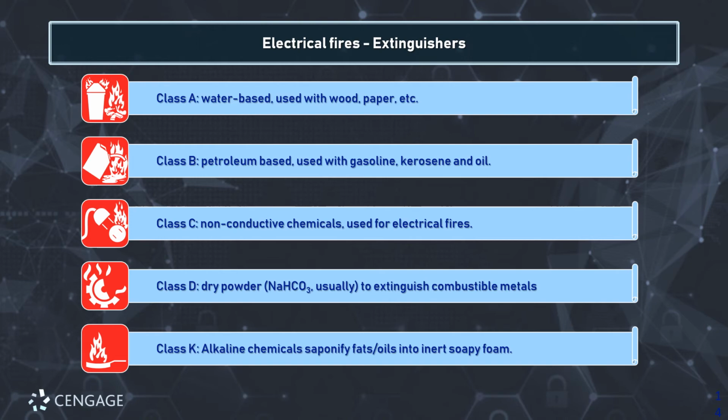If you do that with oil, because oil likes to form very similar in biology to what we call a lipid bilayer, it takes these little bitty pockets of water and spreads them out, and it gives them just enough insulation to where they don't flash vaporize. But what they do is they start to boil, which means that they fling the oil that surrounds them outwards into a cloud.